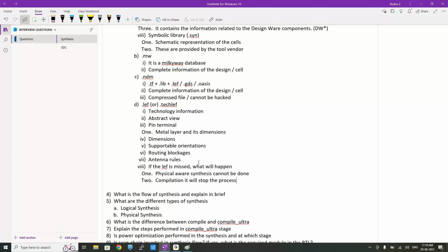Clear? Why I'm saying you will not have unresolved references or linking errors is because all the logical libraries information is provided. That means each and every instance and module information is provided. The only part pending is physical information, and physical information is just an external support for the optimization. As that is not provided, your optimization will not go ahead.